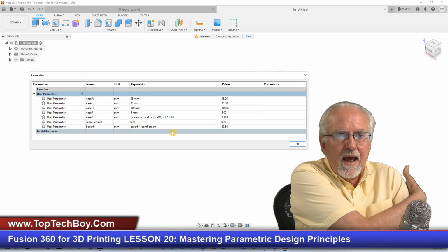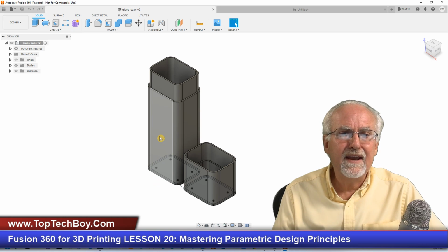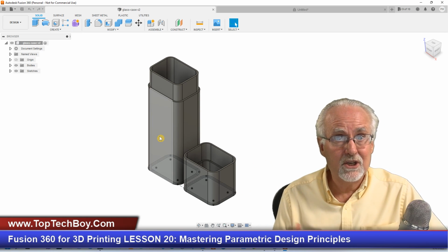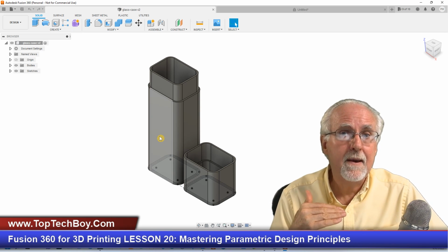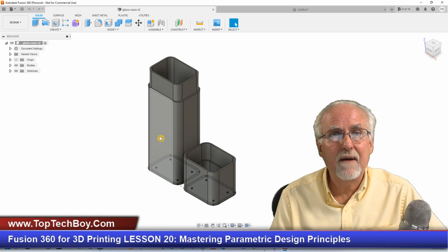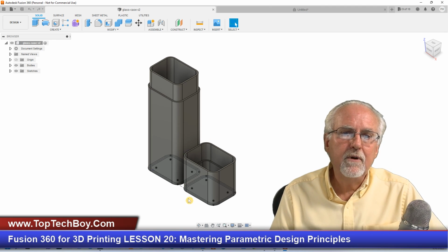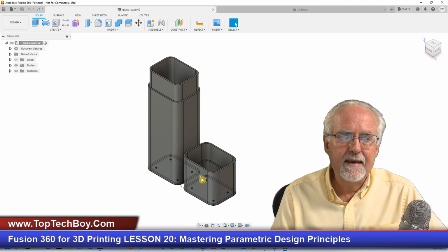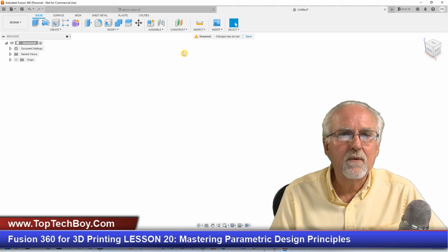Okay, so now, why did I create that parameter even though there's no new information there? Because when I extrude this, now I can just extrude this by the base height. And so I've got that number already in there for that extrusion. Now I'm going to go ahead and make a cap height. How high will the cap be?